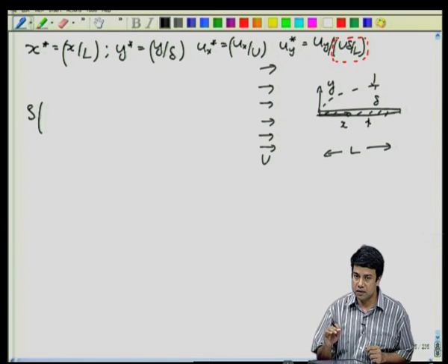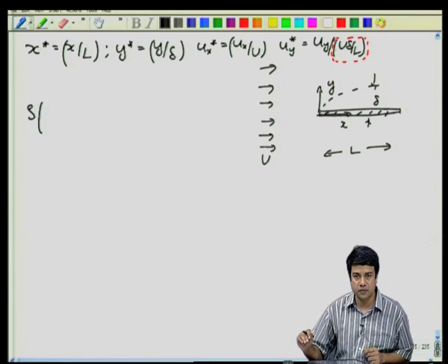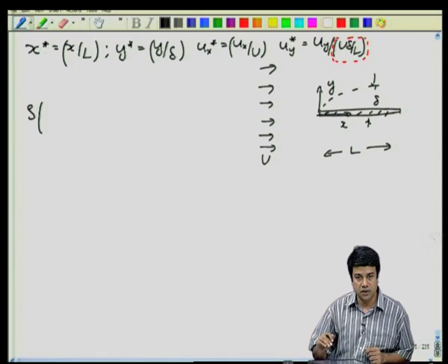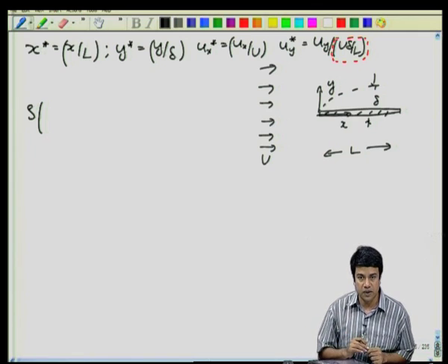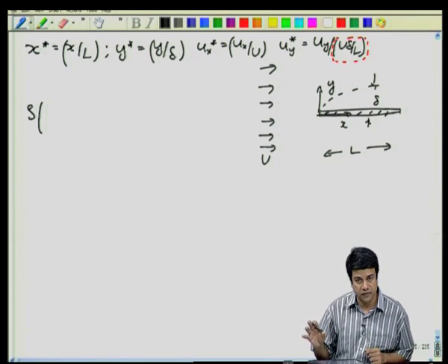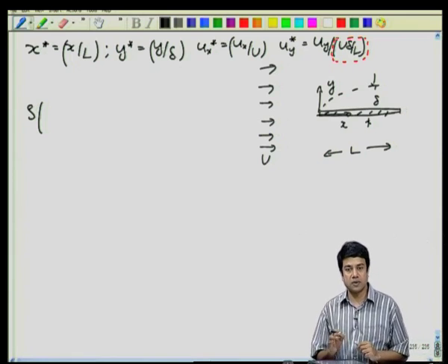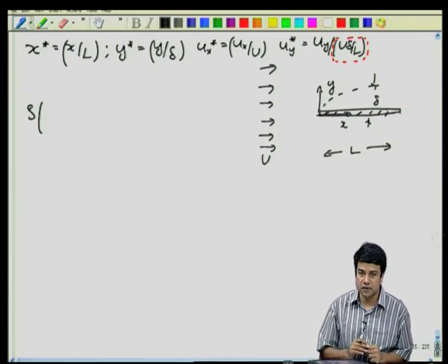We had required that the x velocity has to come to 0 at the plate, that is the tangential velocity has to come to 0 at the plate. The potential flow equations were not giving us that, because we could not satisfy the tangential velocity boundary condition. Therefore, we first analyze the x momentum equation, because somehow we have to get the diffusion or viscous terms and the inertial terms to be comparable in order to satisfy this boundary condition for the x velocity.